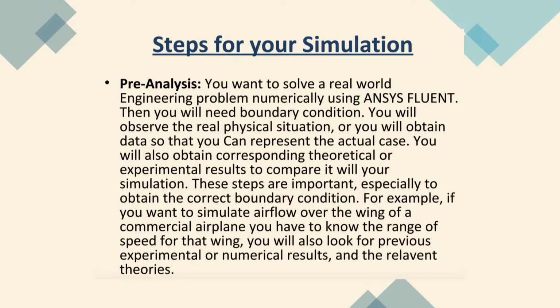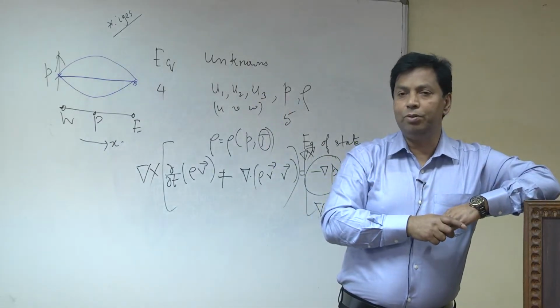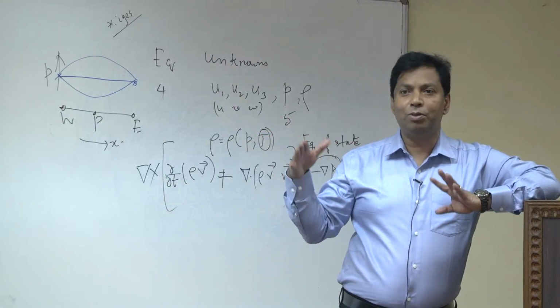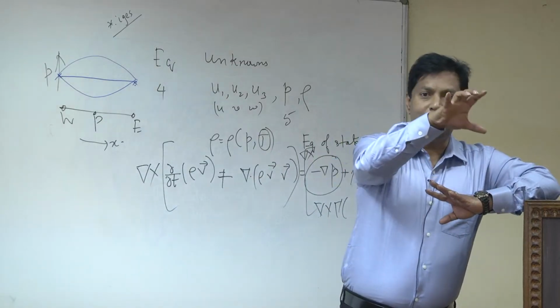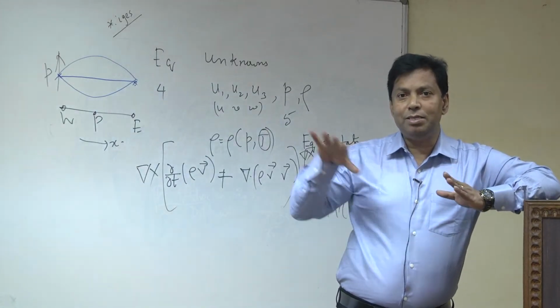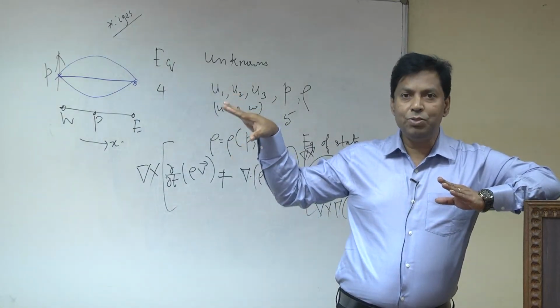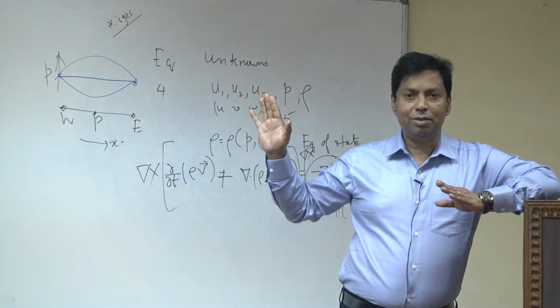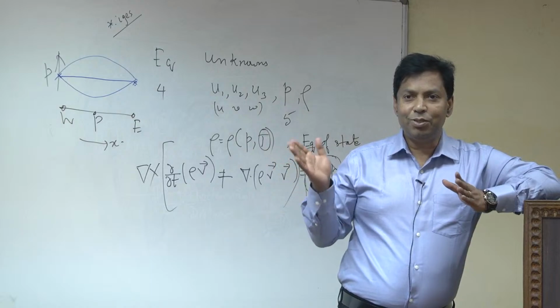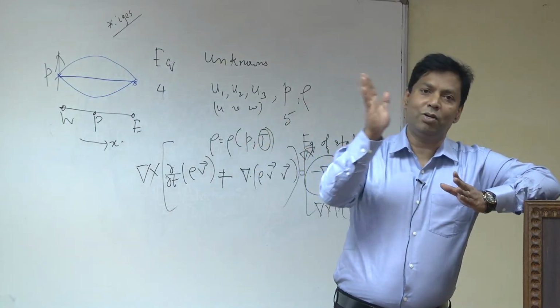So, in our CFD research, what we do for validation, for example, is this: we are solving one totally new problem, one that is not solved yet, so no results are available. So, how can you validate? Before that, for the validation, you have to find a case very similar or close to your problem, maybe someone already did it. Just get their information, set up based on their data, get the results and then compare. If they match, it means your solver and the setup you did are correct. That is the way we validate, because if somebody has already done it, we do not need to do it again. So, you can take some already published results and compare your results with them.